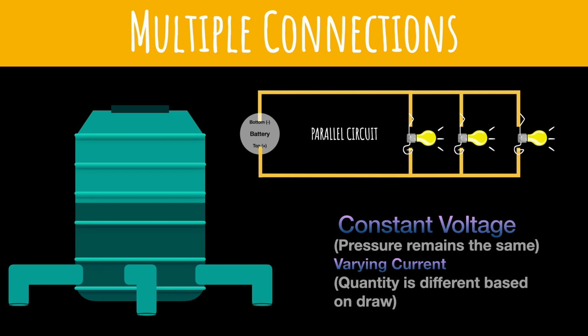There's positives and negatives to both of these circuits. That is, in a series circuit, even if one light goes out, then the whole circuit is out. Whereas in a parallel circuit, you could have one of the LEDs go out, but still have connection to the rest of them, and the rest of them could light up. So if you understand the difference between series and parallel circuits and how voltage and current varies between them, we kind of accomplished the goal with this module. That's the primary learning objective for this module.